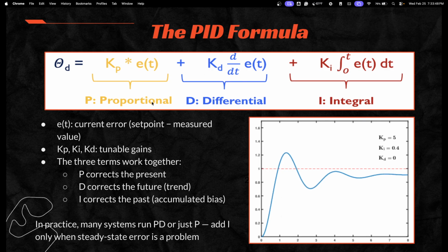So the error term that I mentioned before is your actual input minus what the vehicle actually did. So basically, you would have a variable. This is the variable that you will be adjusting to fine tune your PID, and then this is the error. So with the differential part, so that's the proportional part. The differential part is pretty much how fast your error is changing.